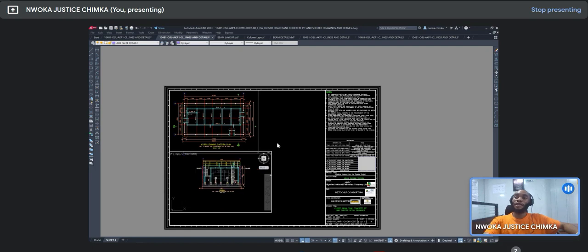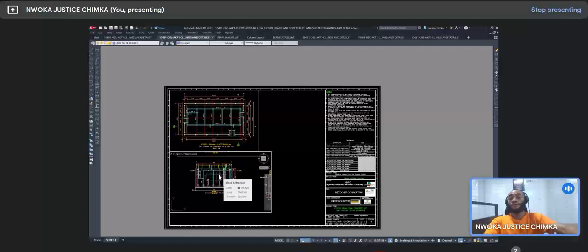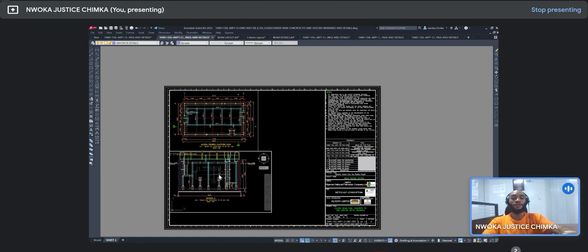Okay, so right now you can see that I have just zoomed and I've just removed this drawing from the scale. So I'll have to redo it by bringing it back to this scale here. I'll just do that again by using the same thing, Z enter, 1 all over 35, and then I press XP and then enter. Okay, that's fine. So right now I have just set this plan into scale.